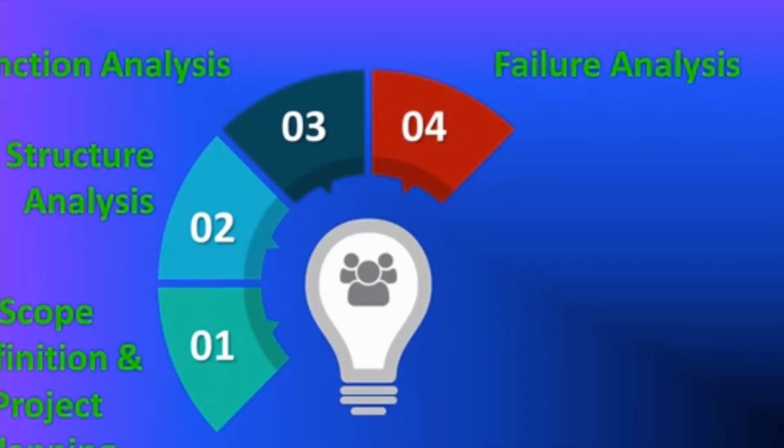It helps to identify failure causes, modes, and effects, and show their relationship to enable risk assessment. In the new revision, there is a change in the order of columns in the PFMEA form to make the failure chain follow the sequence of failure effect, failure mode, and failure cause.